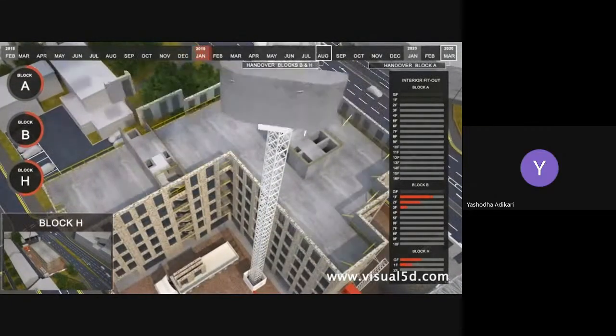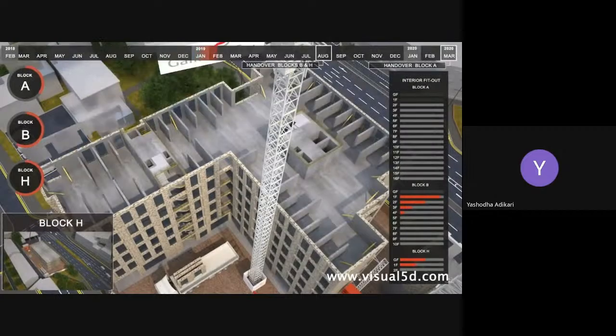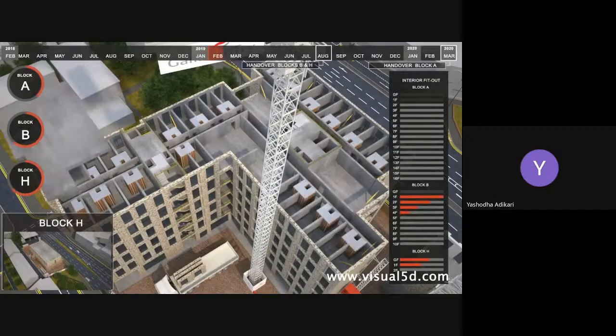All external walls are lifted into position first to enable them to be line and levelled, followed by the internal walls to tie them in. It is at this point that we will lift in the finished bathroom pods. Finally, the solid concrete floors will be lifted on top of the floor plate.